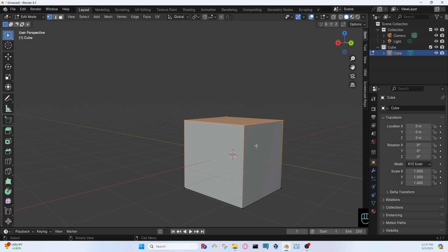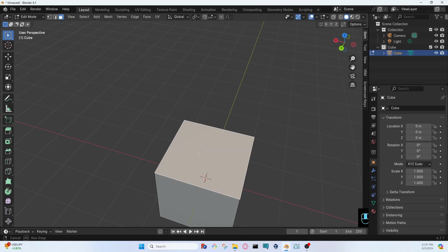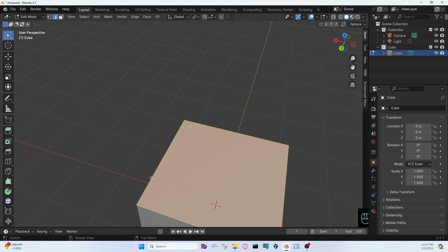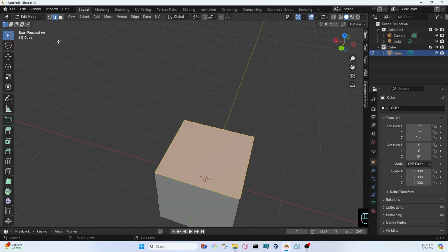Oh, and let me go ahead and add, if you switch between modes, like if you select a face and then you go back to vertice or you go back to edge, you will see that I have these 4 edges selected because I had that whole face. It remembers what selection you had, and it applies the applicable selection to whatever select mode you're in. So if I go to vertice and I select just these 2 vertices and then I go to edge mode, it will now select that edge. If I go to face mode, it will not select anything because that is not enough edges to cover a face.